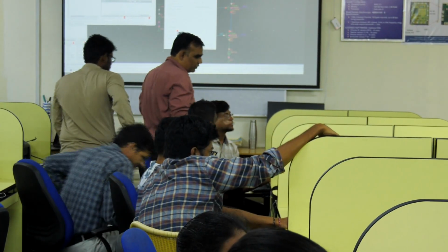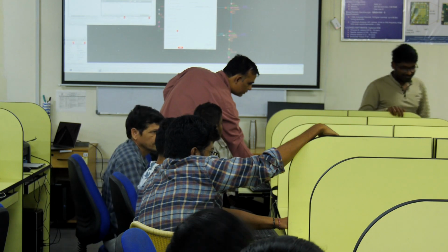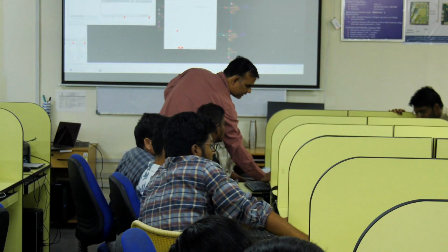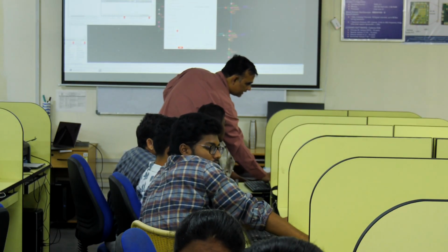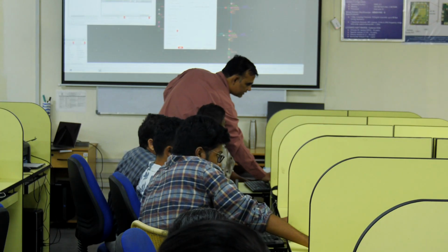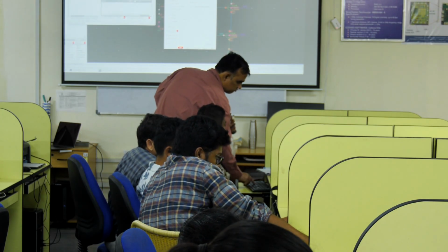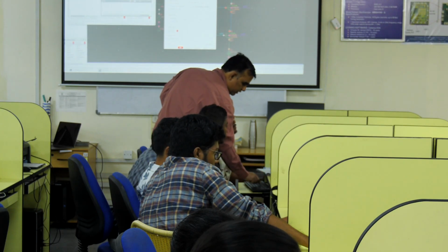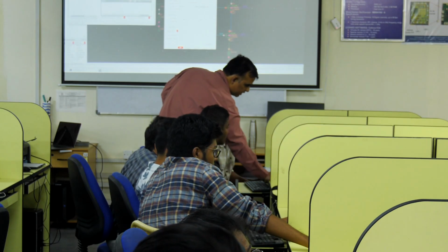So, what do you want to do? You need to see what do we want to plot. We want to see this value as an output. Okay? And then we want to say what kind of simulation we want. We want a DC simulation. We want to start at say 1 femto or even 1 pico, and we want to go till 1 micro. Let's go till micro.